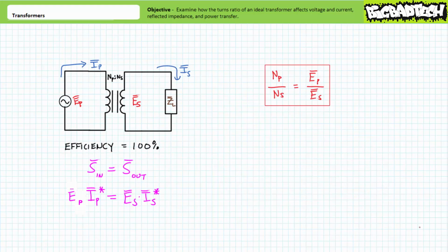Given the function of a transformer is to step up or step down voltage, a given power is a product of voltage and current. If voltage at the secondary output is higher than the primary input, current drawn from the primary must proportionally increase to achieve the required power transfer. Conversely, if voltage at the secondary output is lower than the primary input voltage, current drawn by the primary needn't be as large to transfer the required amount of power.